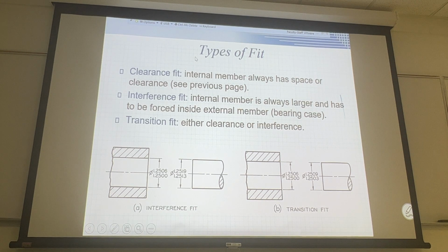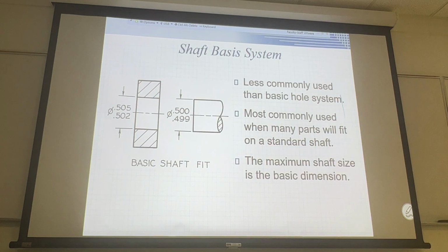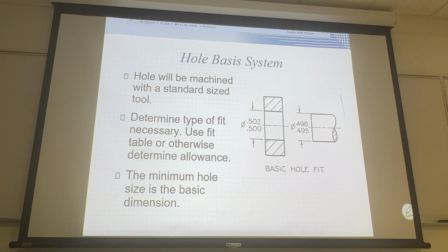So there are different types of fit. This is hole base: you take the hole as the base, so the shaft should be a little smaller.